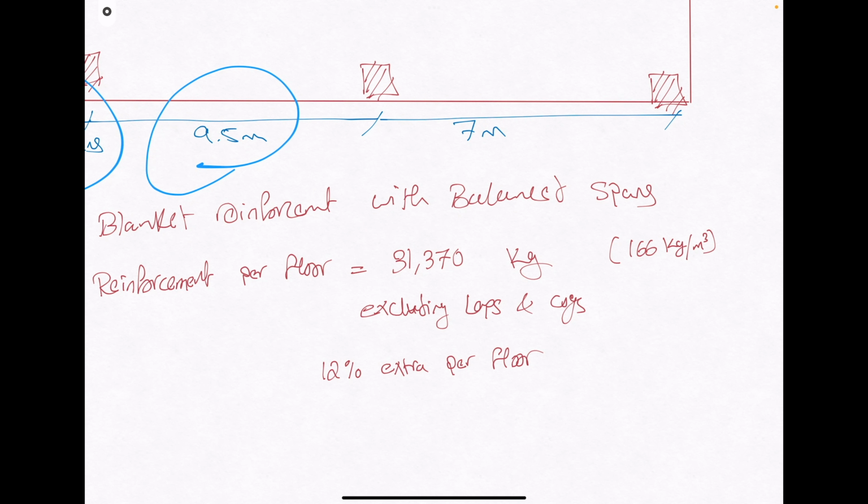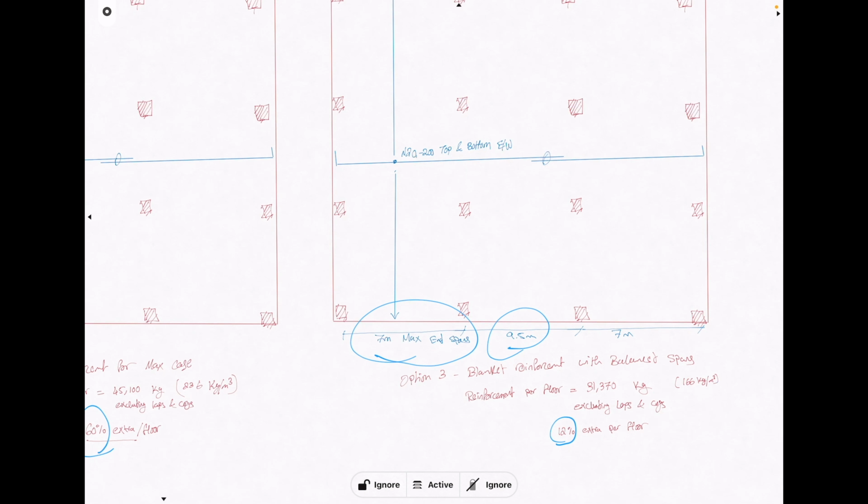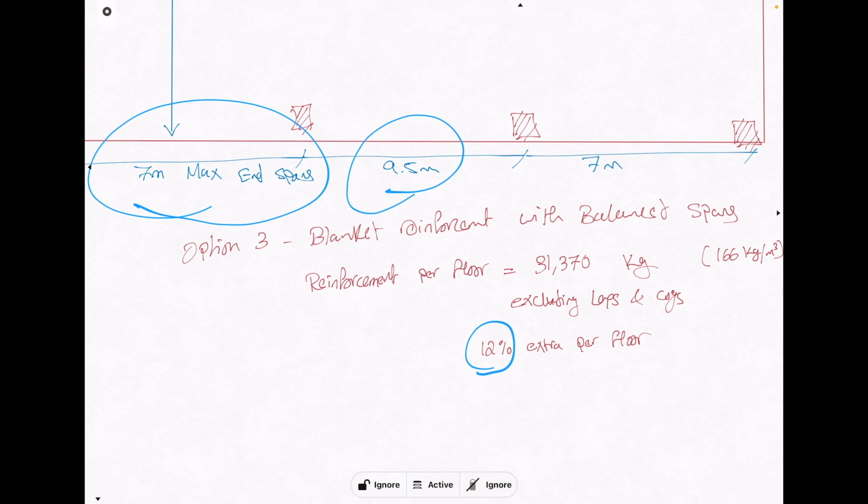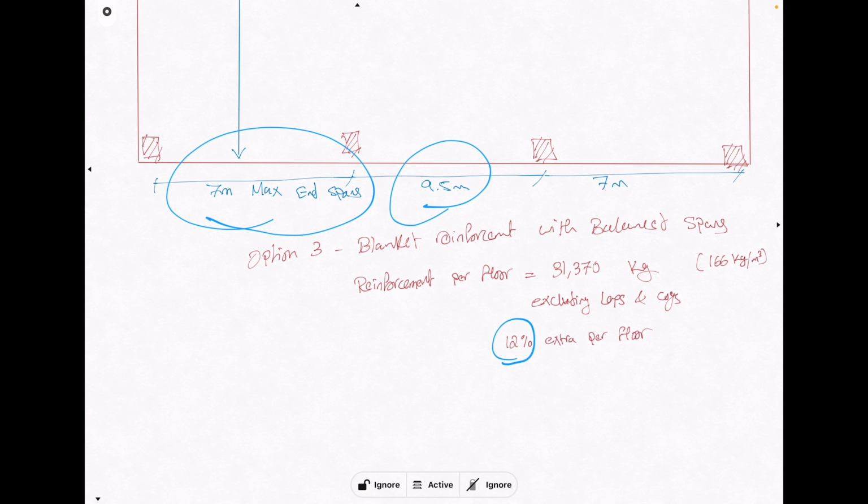and this is gonna give me about 31.3 tons, which is only about 12% extra compared to the original proposal. So I achieved my simplicity in design, and I achieved a very efficient design still. It's not the most efficient, but it's as practical as possible. Sometimes that is part of being efficient, so there's less chance of errors happening on site. And generally 5 to 15% within the absolute minimum is acceptable in practice.